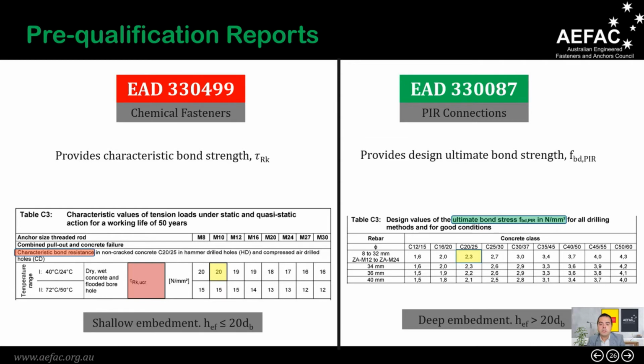In the post-install reinforcing bar application, the actual strength of the chemicals is not utilized, but is limited to the bond strength of cast-in reinforcing bars.